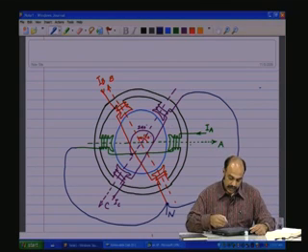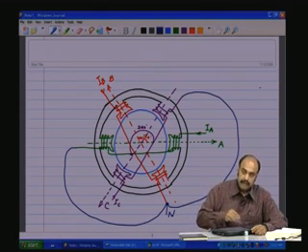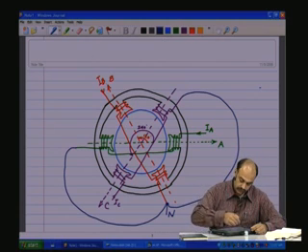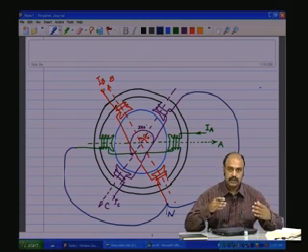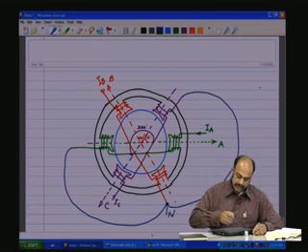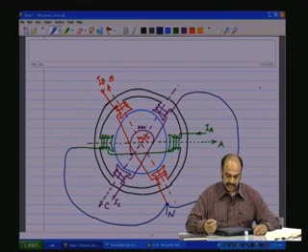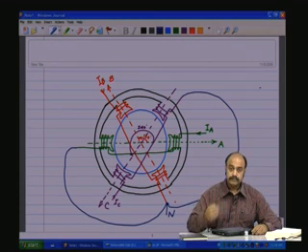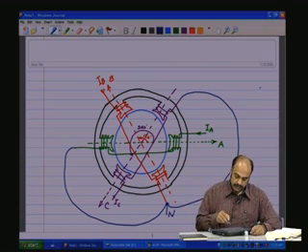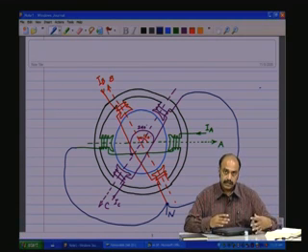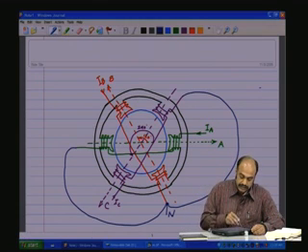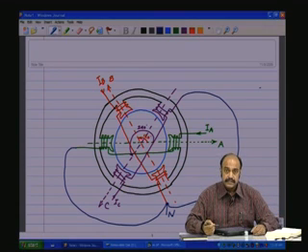flowing. So IA is flowing through the A phase pole, this is stationary, fixed, and IB is flowing through the B phase pole, that is also stationary and fixed in space, 120 degrees shifted with respect to the A phase pole, and IC is flowing through the C phase pole and the C phase axis, and that is also shifted 240 degrees with respect to the A phase, this one, in this manner. So this is a star connected induction motor. The stator coils are star connected with the currents IA, IB, IC flowing in this manner.